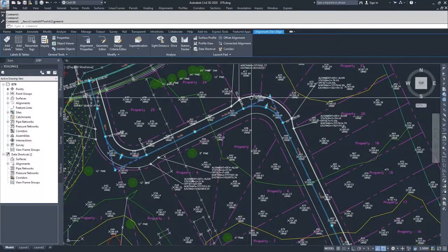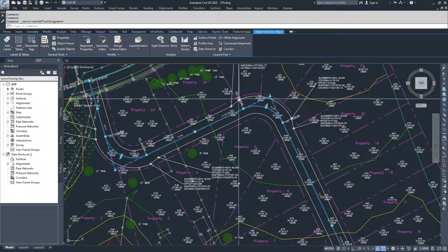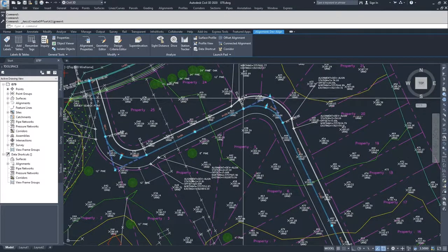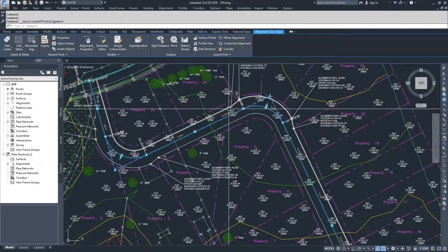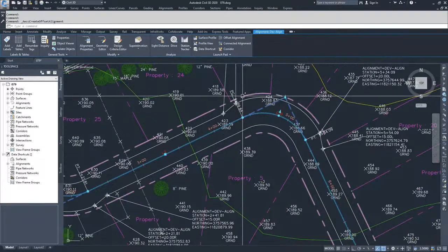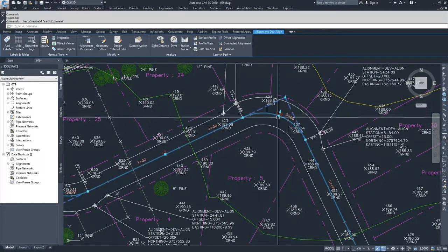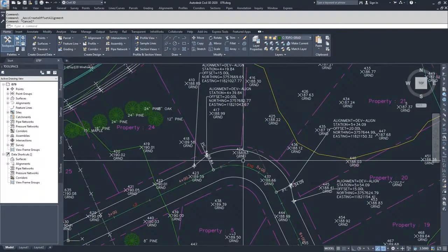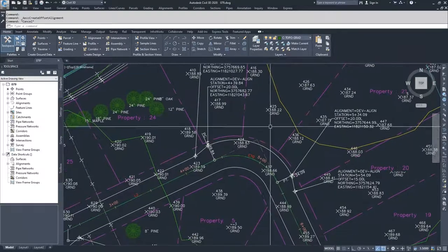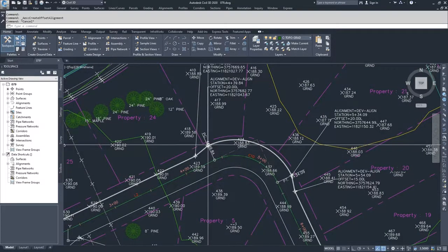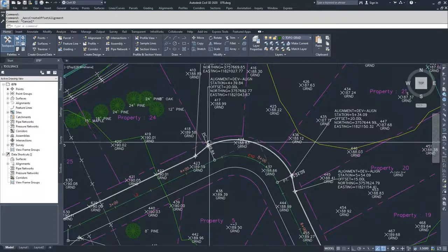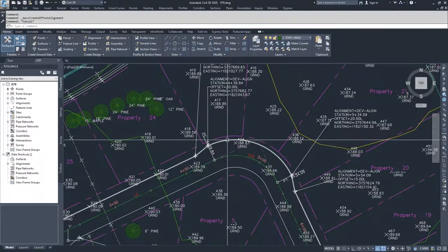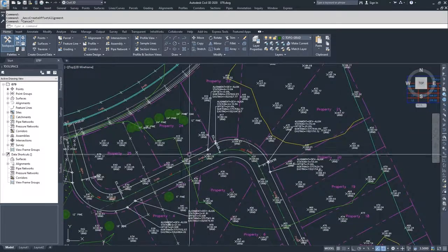And then I had to recreate the widenings that we had before. We set them as 20 feet so that they would be a 5-foot offset from our 15-foot. And then they have linear transitions at 20 feet long set at the corners or the radiuses of our curves here. If you want to do that yourself, otherwise you can use the provided files, make sure that your transitions link between these points that we have here originally, because these points are associated with a point in space, not associated to the original offset alignments. So we did these updates.